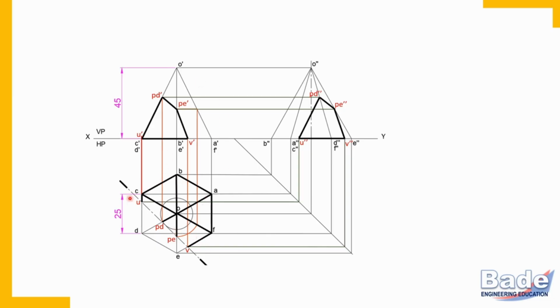Check here. Section. Remember in front view this is left side and this is right side. Left side and right side. So left side with reference to this cutting plane. Left side is removed, right side is retained. So make here right side of the section dark. Side view. You need not check each and every edge. Try to understand.